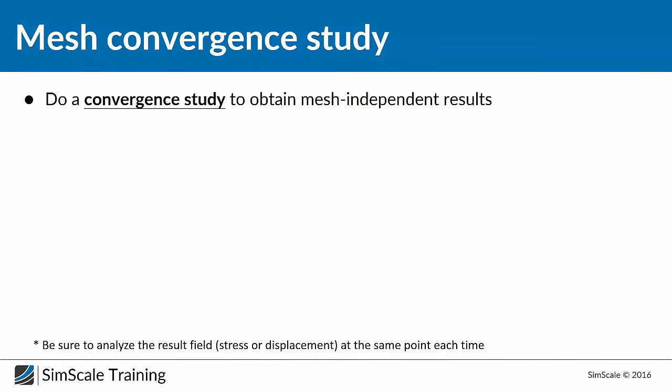On the other hand, we want to make sure our simulation results are of high quality, because in the end we want to use this result to improve a product later on. And the quality of a simulation is very much related to the right mesh size. And having a too coarse mesh can really create serious problems. The simulation will work a lot of times, but the results are crap.